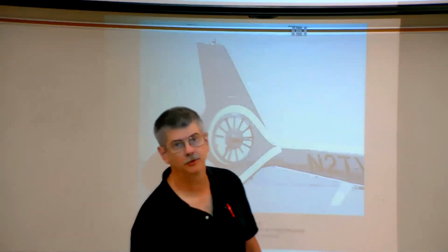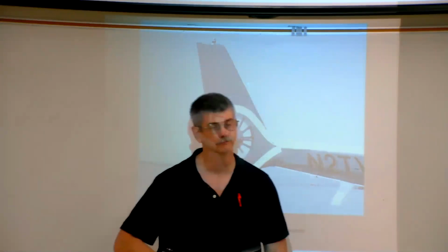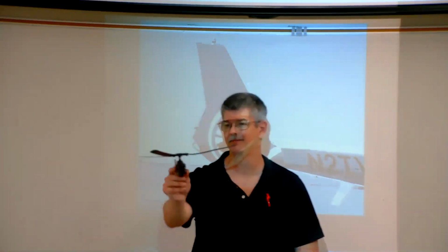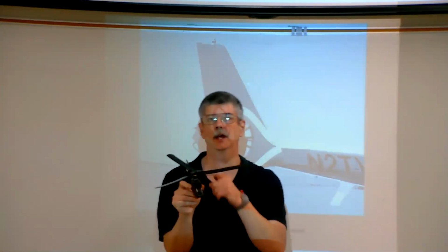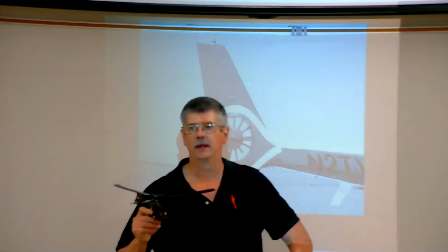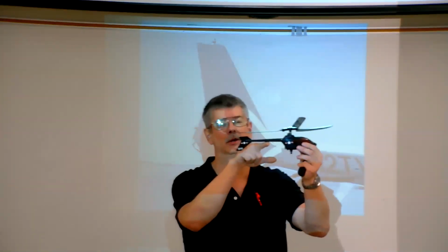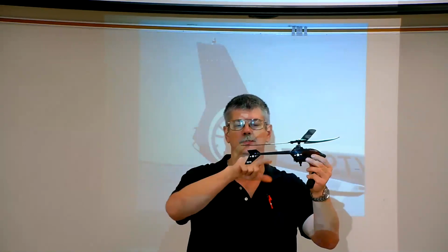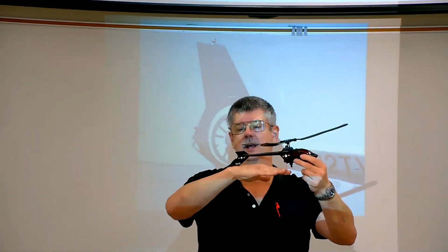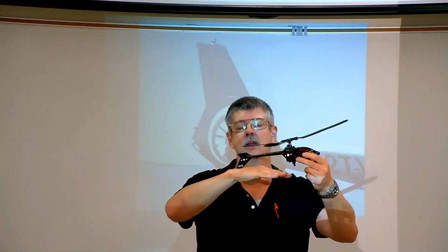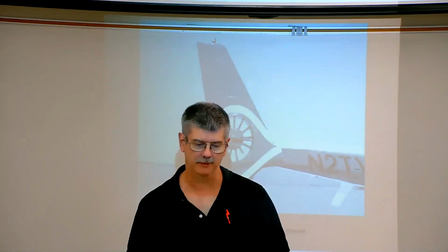If you lose the tail rotor, you lose control, and you're going to crash. So a lot of times, if the tail rotor is exposed, there's going to be a very big metal bar that goes down. The reason for that is when they come in to land, if they come down with the tail down, that bar prevents the tail rotor from hitting the ground.